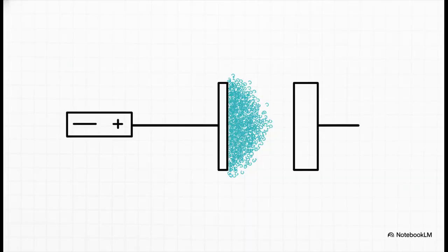When you apply a steady, direct current, a tiny little bit of current flows for just a split second to charge it up. But after that, nothing. It's a total dead end. It basically acts like a break in the wire, like an open switch. This whole ability to block DC is super important for things like filtering power or tuning radios.